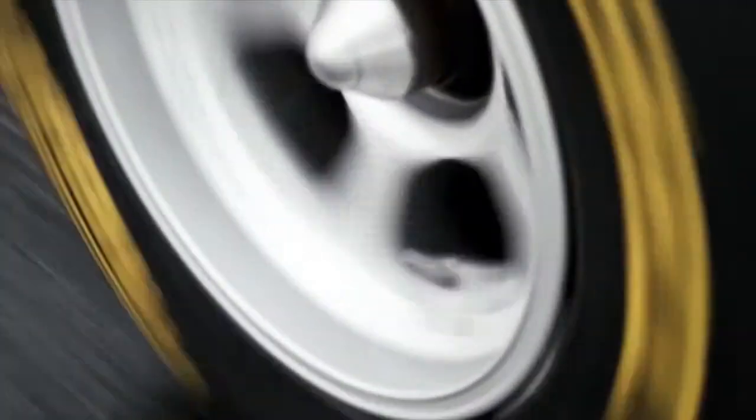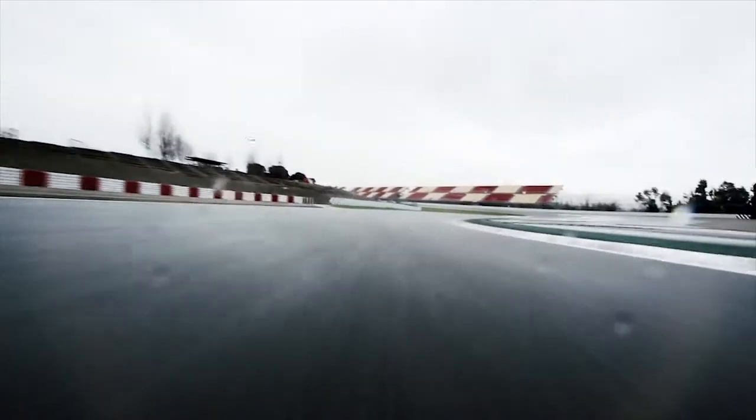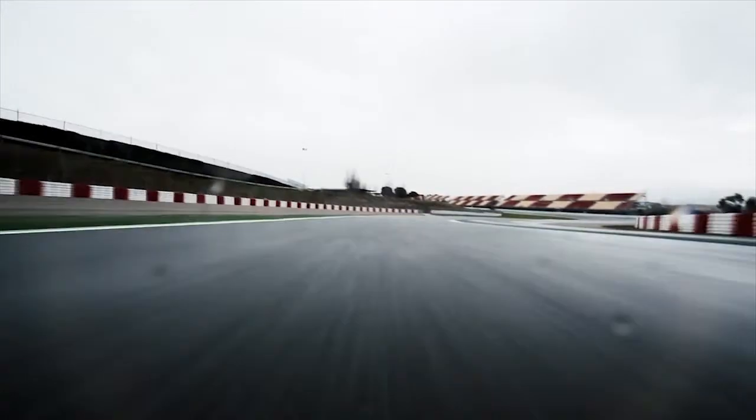conditions such as the weather, the state of the tyres, the consistent behaviour of the driver, they're things that are changing. However small, they're changing. However subtly, they're changing all the time. So track testing is the most realistic way of testing, but it's also the least repeatable because of these changing conditions. And track testing also wears out the powertrain, wears out the tyres, and so costs much more than other research methods. Model testing costs less.